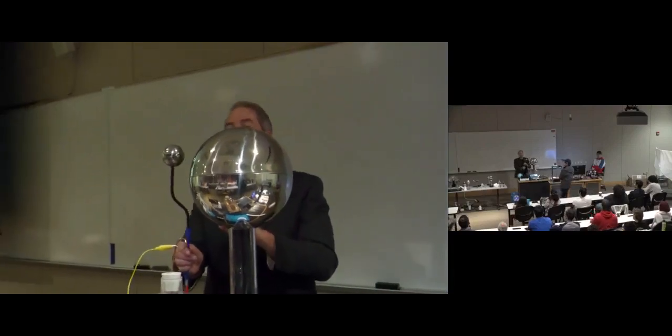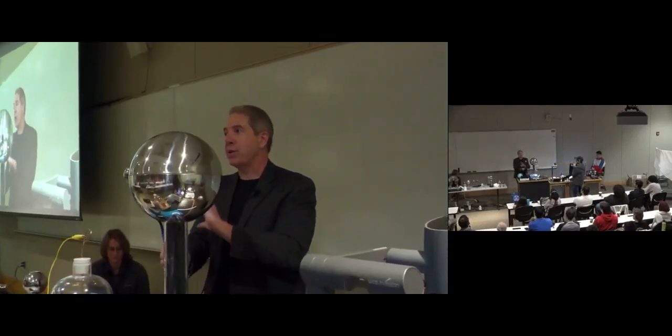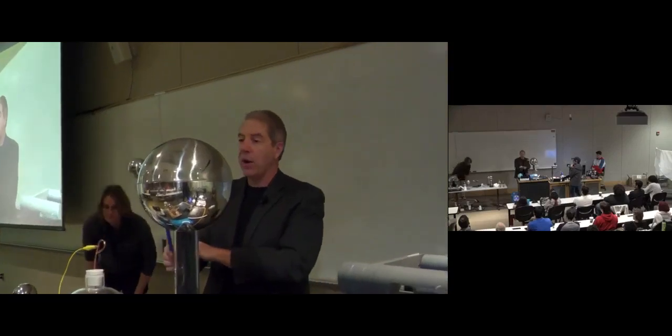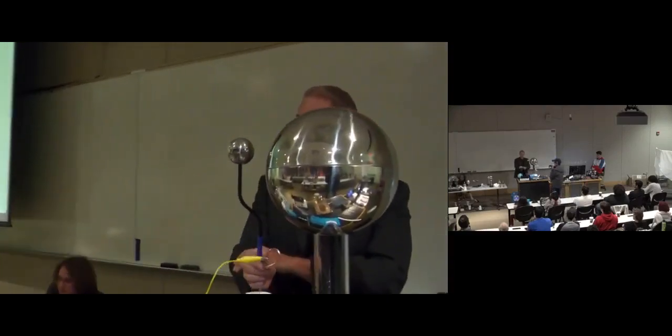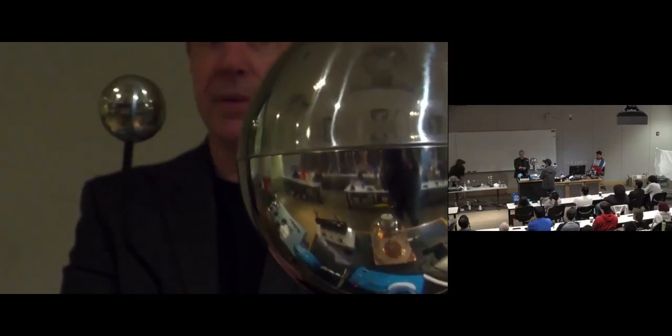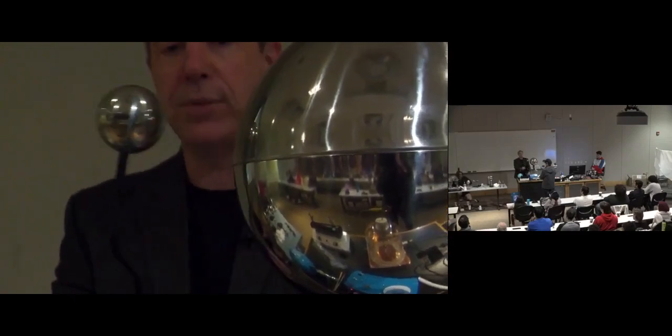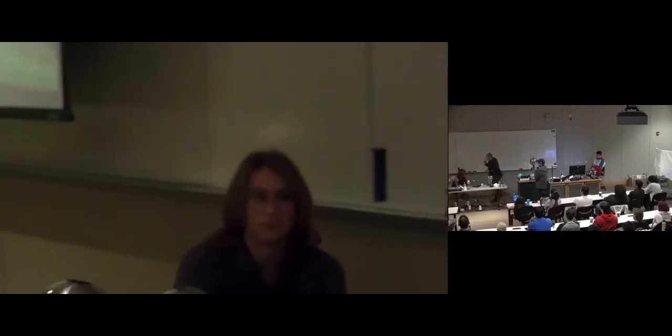In high voltage, air breakdown is approximately 30,000 volts per centimeter. So that's about 5 centimeters, so 150,000 volts. That's how we measure it. And actually, at some point, that was how they measured voltage. It's a little bit different depending upon the moisture in the air and the shape of my domes. But we got about 150,000. Over here, we had a few thousand.